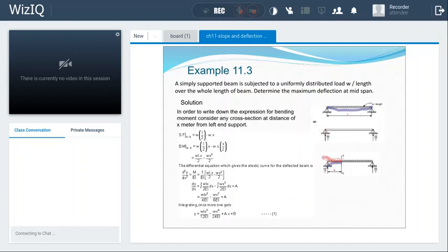Now we have these two bending moments. So here we write the equation with plus and minus sign for hogging. And always remember that all downward loads will be giving you hogging bending moment. So we will use minus sign for those. And all upward forces will give you sagging bending moment. So we can substitute here the values WL by 2 into X, the bending moment due to this reaction, and then the bending moment due to this uniform load, W into X, because the length is X meter. We are considering only this much portion on the left hand side.